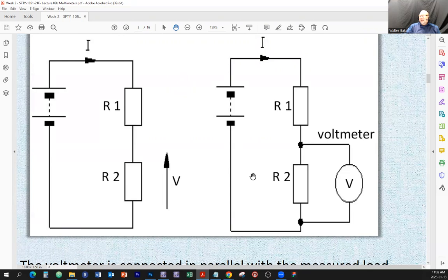What is the idea of taking a measurement of a live circuit? Well, the first and most important idea is to not alter the behavior of the circuit, which means that the resistance of this voltmeter is going to have to be as high as possible, to be comparable with the resistance of the air, which is also high.